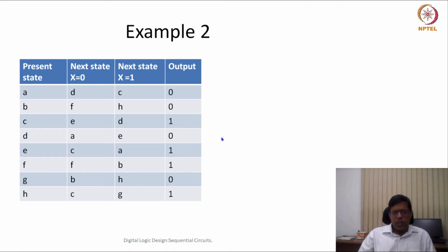So if we see here, these 2 rows are different. Even if you spend a couple more minutes, you can pause the video for some time and look at these rows carefully. You will not be able to find any opportunity. So can we still say that this is an optimized state machine? When we have such a state machine where there is no obvious reason to merge, or no obvious reason to say that these 2 states are the same, then what should we do?